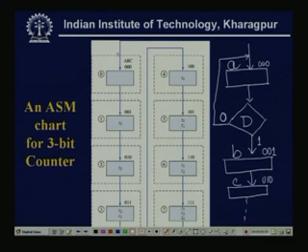So, before actually the input of this first state symbol, this will be added. That means one state's initial state symbol followed by a decision symbol, and if it is 0, then again it will stay in the same state, means initial state, and it starts counting when it is true. So, actually this is the exit point, if this condition is true, then it starts counting, and in that way we can represent the ASM chart.